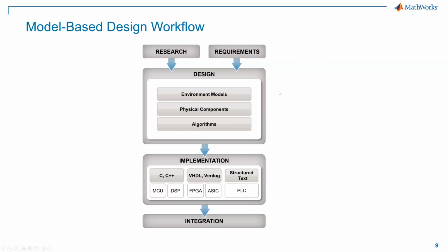Let's understand that. But first, what is the model-based design workflow? In the model-based design workflow, we are creating a digital twin of the process and performing the complete process over it, deciding whether it will perform as per our requirements. So let's deep dive and understand the benefits of the model-based design workflow. Here we can define the requirements in the model. If the requirements are defined in the model, and later on we make any changes in the requirements, we will be able to see the effect on the final output, final design, or our final product, which helps us in rapid prototyping.